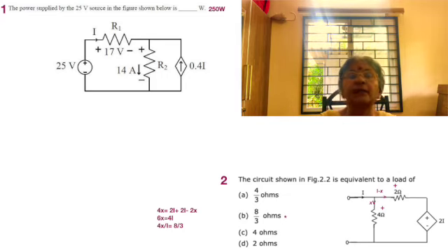For that you again use Kirchhoff's voltage law. It tells us that the voltage across the 4 ohm resistor has to be balanced by the parallel branch, which comprises both the 2I source as also the 2 ohms through which a current flows, which is equal to I minus X, because X is flowing through the 4 ohm resistor. Balancing them together, we see that 4X is equal to 2I, which is a rise when you look at the parallel branch, and then the next rise, and that's why the plus sign is given, is 2 ohms into I minus X, or 2I minus 2X.